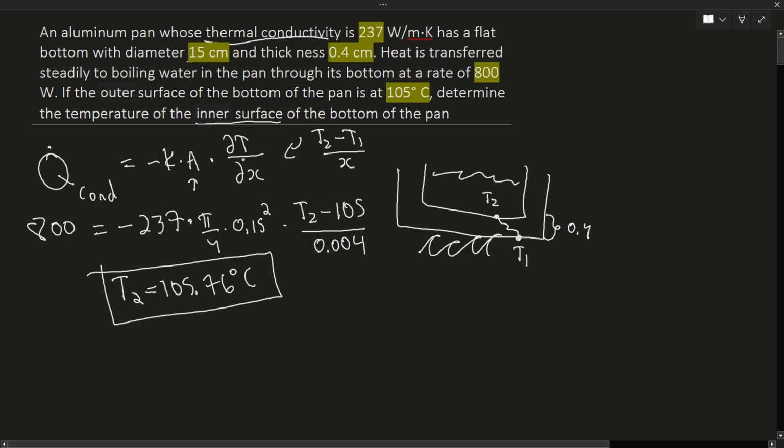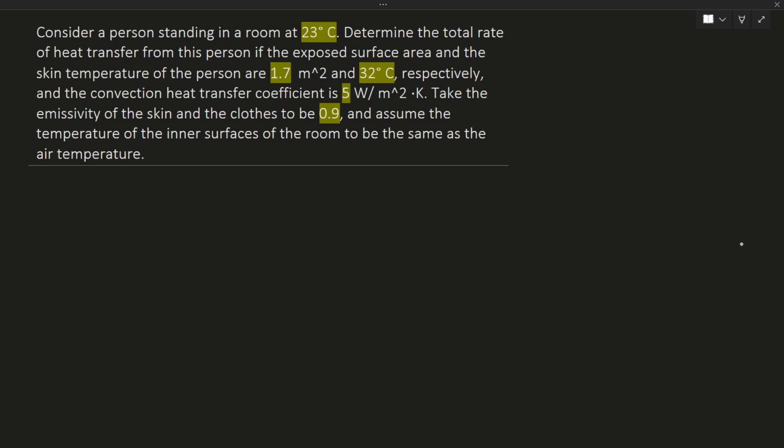The hardest part, honestly, is just this part over here, delta T over delta X. Once you understand how this works and what it actually means, it's super easy, okay? Again, it's where heat is touching a surface. For example, here, T1 is going to be the first part where the heat is touching. And then this body is going to have a certain thickness. Delta T over delta X is how much the temperature is changing over the thickness X. That's it.